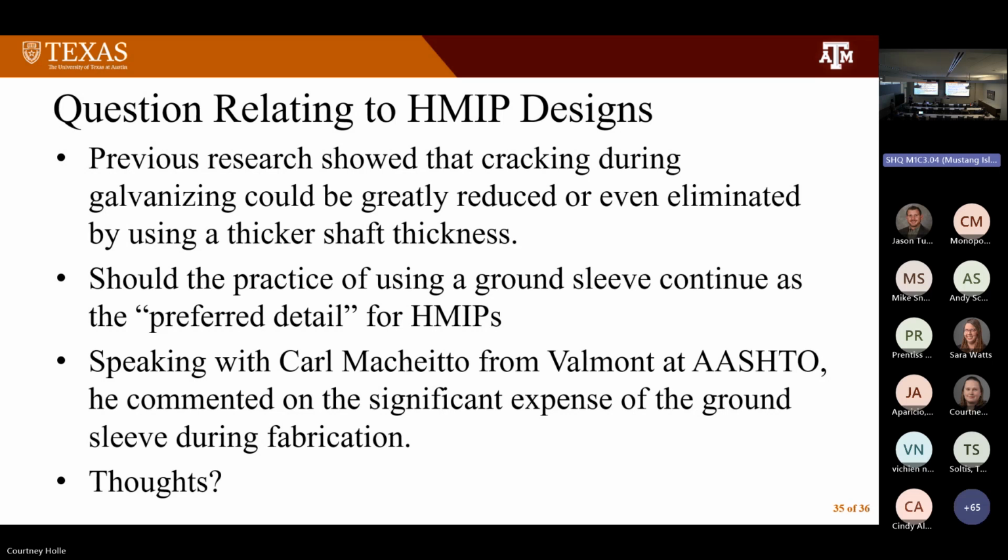So I do think the ground sleeves, our past experience says they do behave pretty well. But it is a lot more complex to weld because you've got a lot more welds to actually look at and so on. Carl online had a comment on that. The AASHTO specification requires that the fabricator UT test after galvanizing to spot any toe cracks. So now they are inspected and so on.